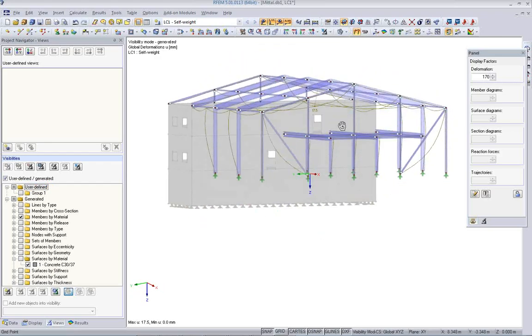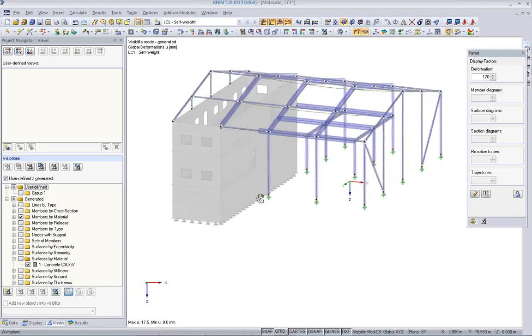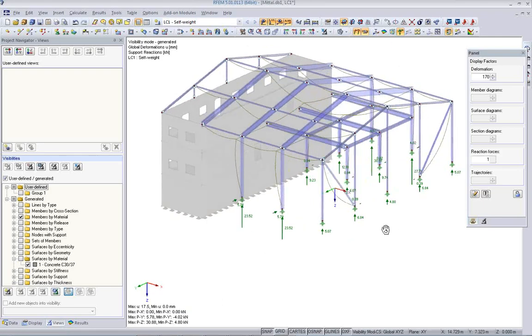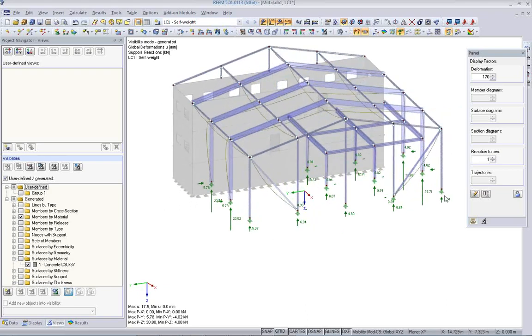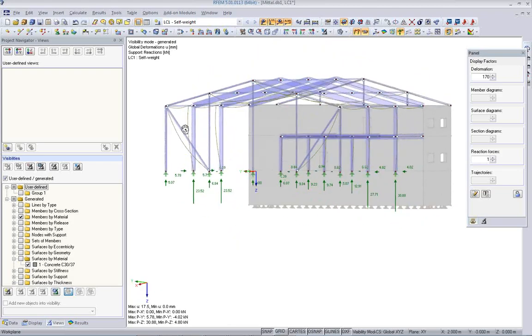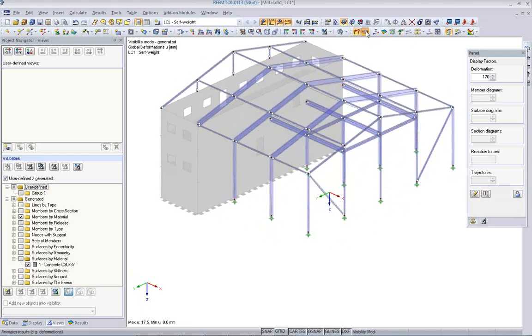So we can see here all the deformation lines of the members. I can animate them, and this way I can usually find if there are some loose parts, and it all looks good. Also, the support condition should be more or less symmetric, which it is at the corner columns, and there's a little bit of difference because here we have this floor structure, but it looks quite okay. So my model is of good quality, and I can continue with the design process.